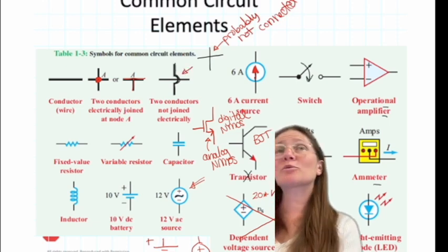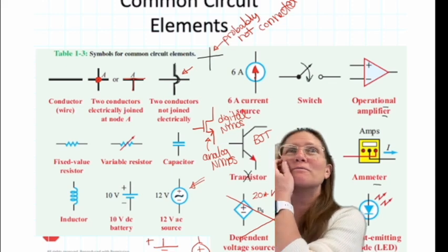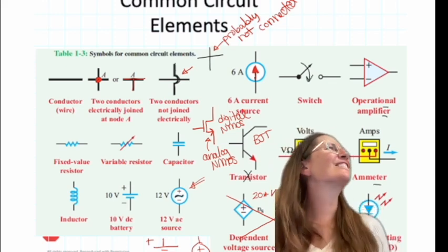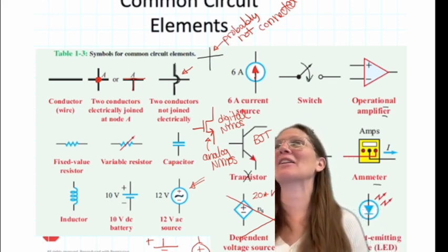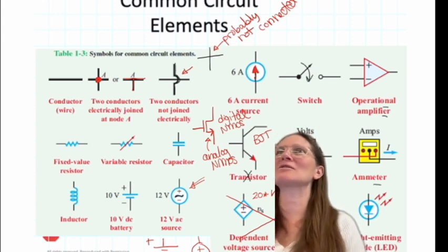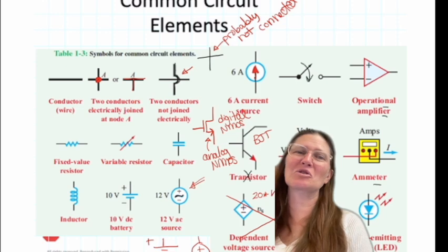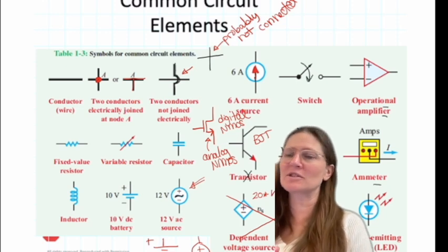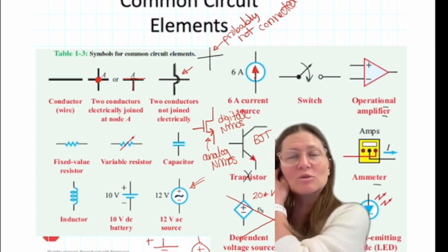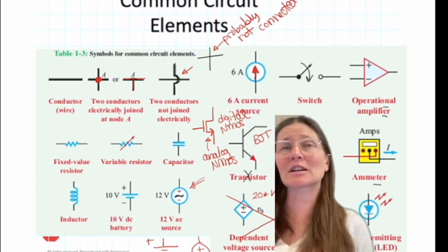This is the nicest way to draw that, but a lot of electrical engineers tend to not always draw the little zag over it to denote that. So you'll see it just crossing. And if it's not a dot with the crossing, then you assume it's not connected there.